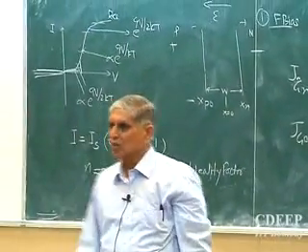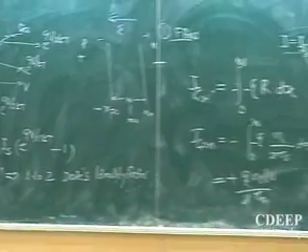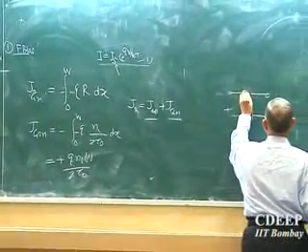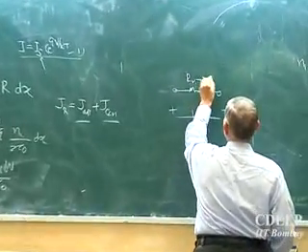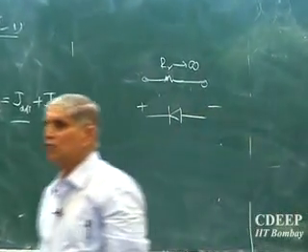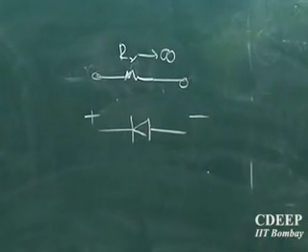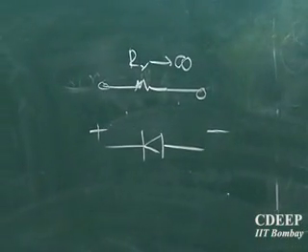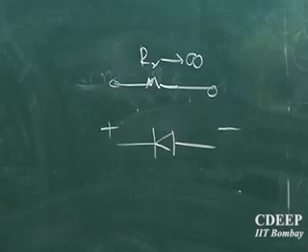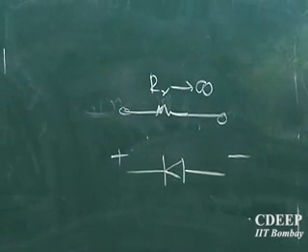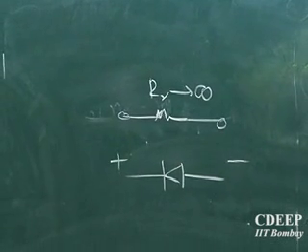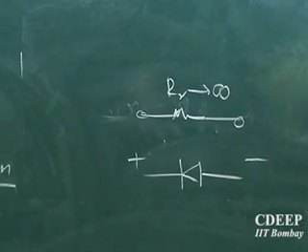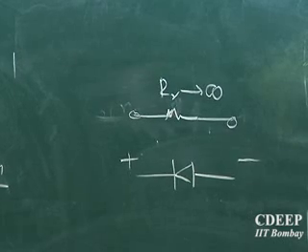I want something like this. This I was not getting. But I say okay, this has some resistance. So I expected this RR should be tending to very large resistance because IS is almost constant, so it should be very large resistance. But in reality we figured out that this RR is not that large as we thought, maybe tens of megaohms. It is certainly not thousands of megaohms, not gigaohms.